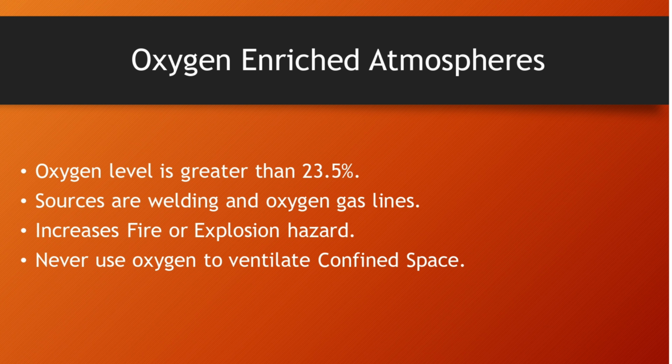Oxygen-enriched atmospheres: oxygen level is greater than 23.5%. Sources are welding and oxygen gas lines. Increases fire or explosion hazard. Never use oxygen to ventilate a confined space.